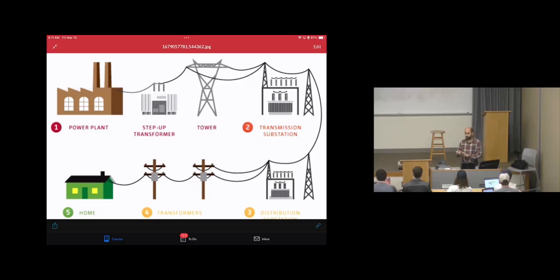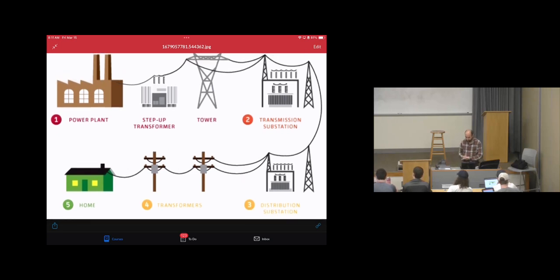Then these large power poles most likely can be in medium voltages, such as 33 kilovolts as one stage, and maybe 11 kilovolts at another stage. And you will see low voltages at the bottom, which can be used to distribute to the local areas. So when we reach, for example, Auburn University, we need to step it down more. It's 33 kilovolts, and we need to step it down so we can use it. Therefore, there will be another substation called the distribution substation. This distribution substation basically will convert from medium voltages to low voltages.